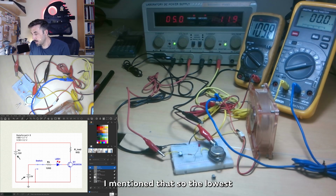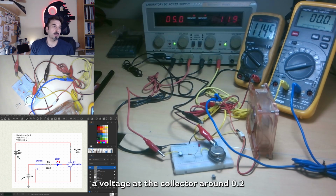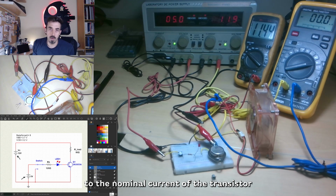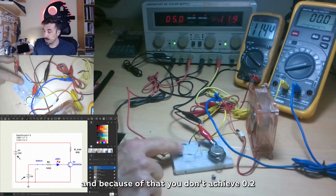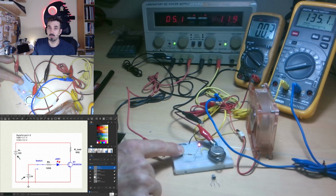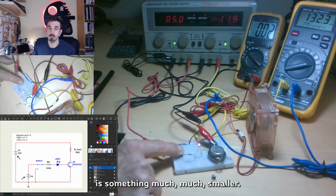I mentioned that you are only going to achieve a voltage at the collector around 0.2 if the current you pass through the collector is close to the nominal current of the transistor. This transistor is rated for a maximum of 15 amps, so we are far away, and because of that you don't achieve 0.2. Instead, you have something much smaller.